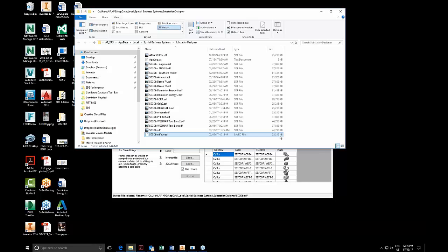No, not really. It only loads when we open Inventor. That's when the database is put into memory. So it's only put in once when you start Inventor. I just want to show that the database does grow when we do this. What we also want to do, if we customize the database, is make backups. So you can see here with the webinar, I've got my first webinar one, I've got my second one, and it's the second one we're using today that's been renamed so that SDS can read it presently. So this is what we're fiddling with here.